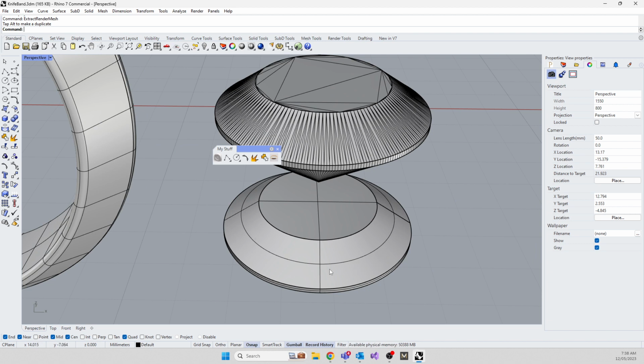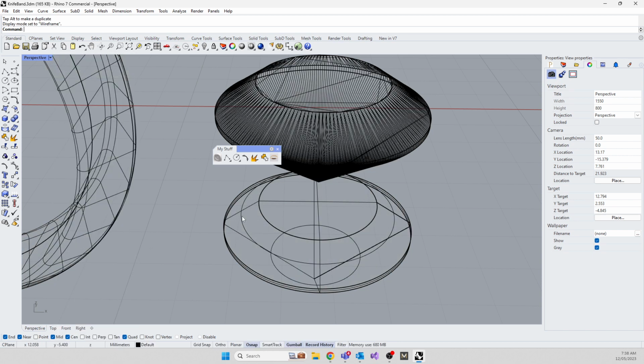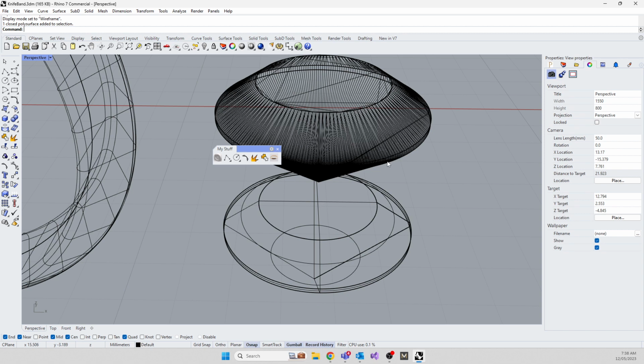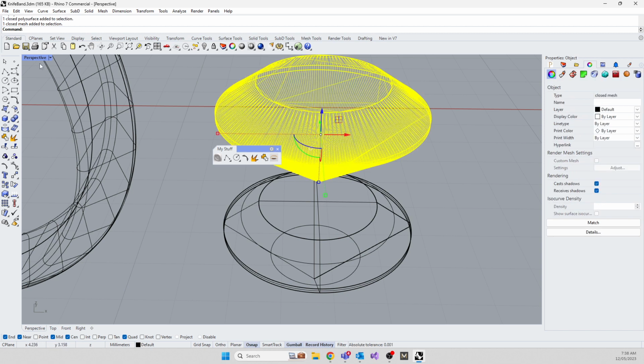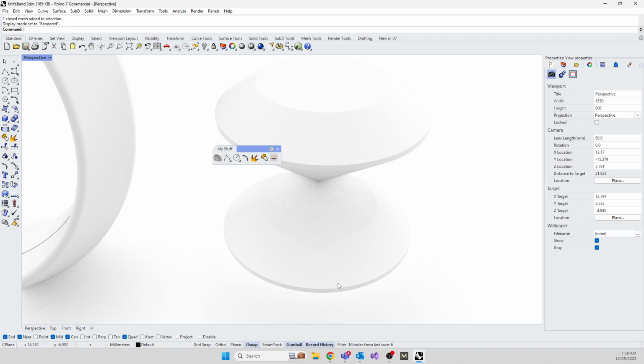So these lines, these isoparms that you're looking at, this is mathematically how Rhino made the surface. For your eyeballs to be able to see it, because this is in wireframe mode, this is literally what it looks like. But you want to see what the part looks like. So internally, Rhino creates a mesh, which your eye can then see. So if you go to rendered mode, you'd see that these two things are identically the same.